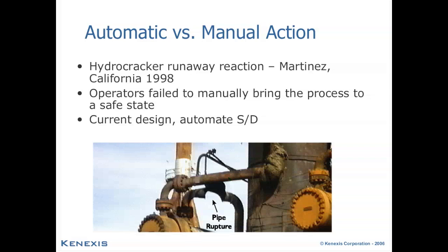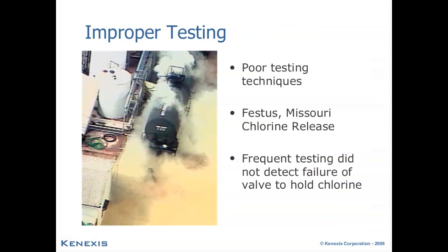During the day of the incident, there were indications that an out-of-control runaway reaction was occurring, but prompt action was not taken in a timely manner, and the result was, unfortunately, a fatal incident involving a pipe failure in the outlet of a reactor because of this particular high-temperature thermal excursion.